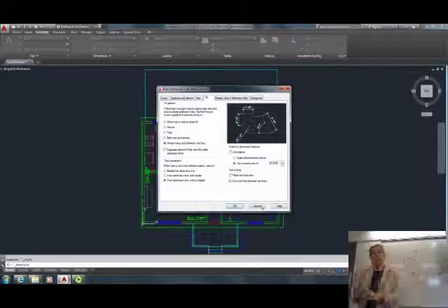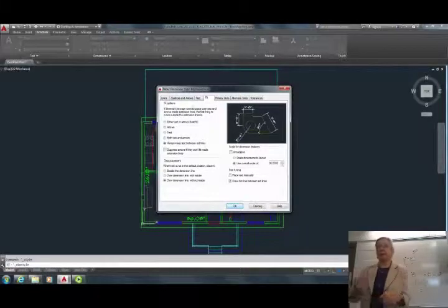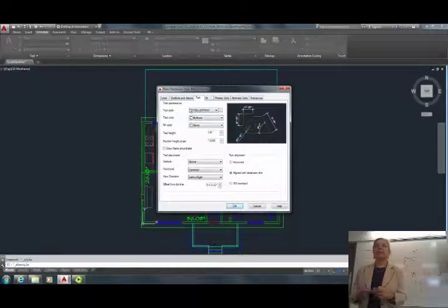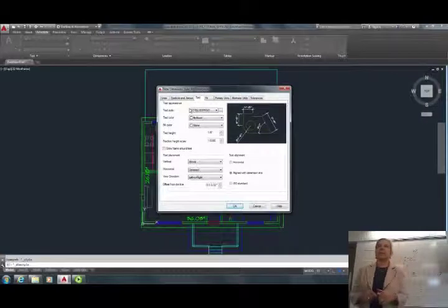Okay, so now that you know this little piece of information, let's give you another smart thing to remember. Let's do text. Let's go to the left now. Text. The next thing to remember that's crucial is that I suggest that you remember these settings as: tell AutoCAD how you want your dimensions to look, and then tell it what scale you'll be printing at, or make it annotative so it changes with the viewport scale.